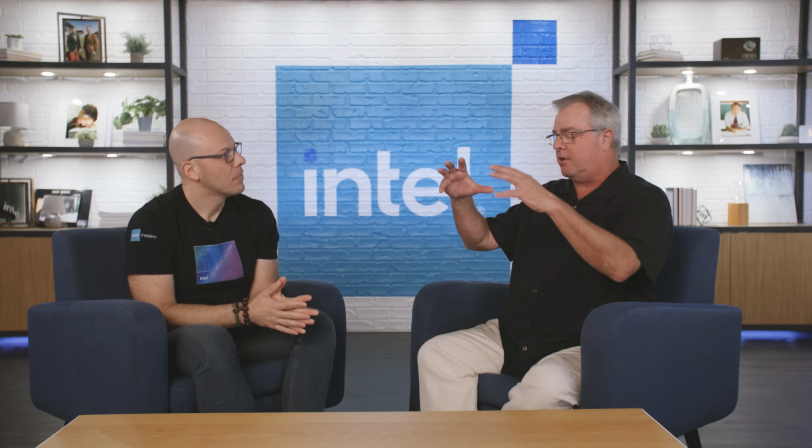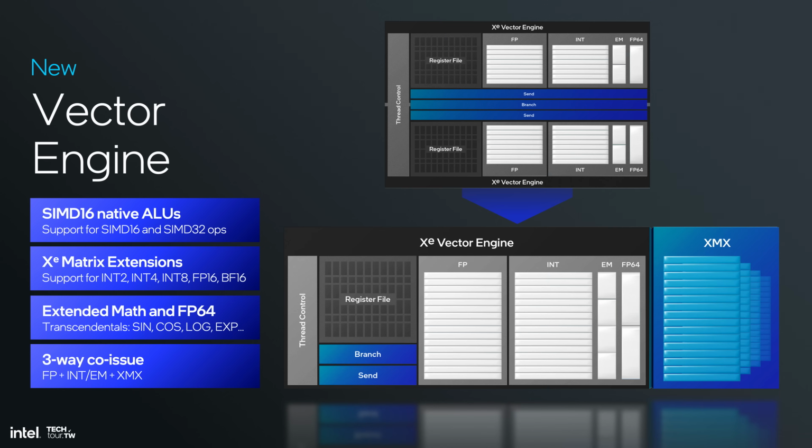Yeah, so when you're starting to dig into the Xe2 architecture, obviously our building block is the render slice, and within the render slice is XeCore. And XeCore, as I mentioned, has a vector unit and a matrix unit, and the vector unit has also had a bunch of enhancements for Xe2. That's our fundamental computational block for most graphics. And it's moving to SIMD16.